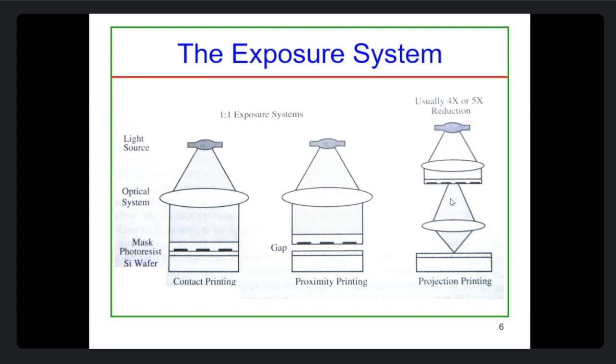So overall, when I'm talking about the real-time aspect, how efficient or how good the projection system is, the central aspect is how efficiently the lens collects the diffracted light, and how well it can refocus the light to make the image on the wafer. The performance, efficiency and effectiveness of the system mainly lie in the ability of these two.